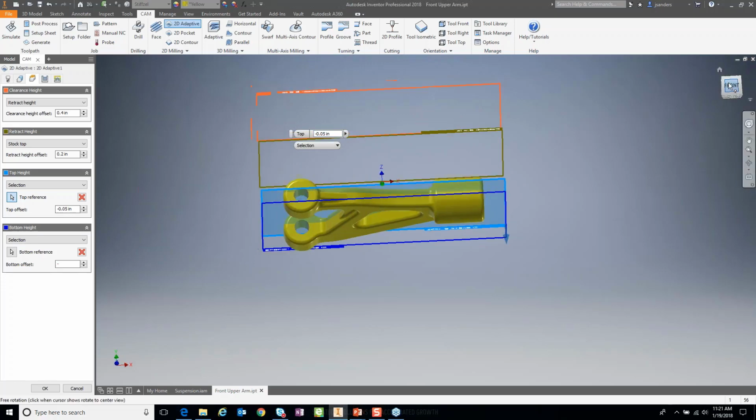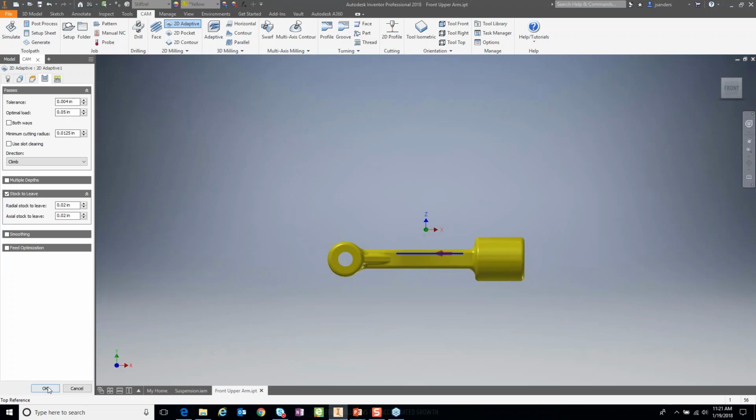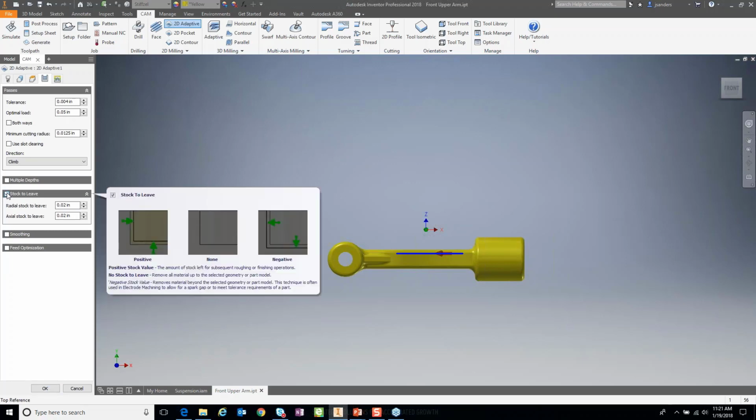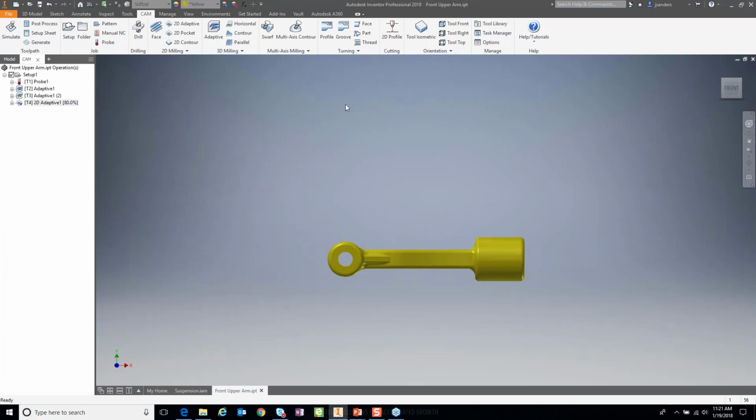And we can look in from a front view and again see our work plane heights quite graphically. Looks like I got the wrong numbers in there, probably my bad. So 0 on the top, negative 50 thousandths on the bottom. The graphical height looks much better. That's exactly what we want. Parameters look okay. I do want to remove this right to all the material, remove it right to size. So I'll take off the offset parameters since that's just a weight reduction pocket.